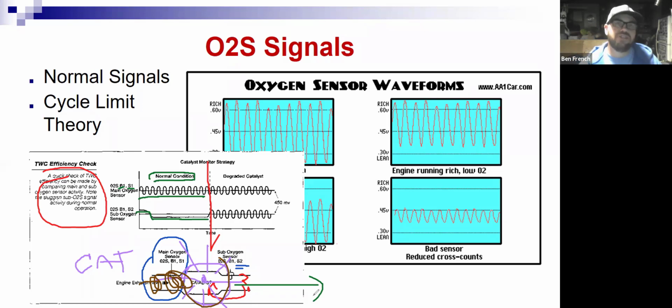Okay, the cat's going to try to burn any emissions the engine doesn't burn up on its own. So the better your engine is running, the less work the cat should have to do. In fact, an engine that's running really, really good, that's well designed, I've found time after time that it can meet the California state emission standards without that catalytic converter on there most of the time. When it's nice and hot and running really good. But the cat helps it out to get it not just to passing, but below passing, and to make sure under all operating modes that it is having low emissions.